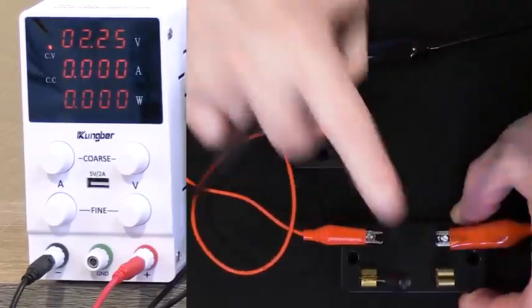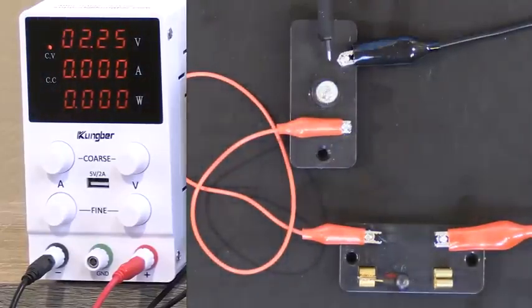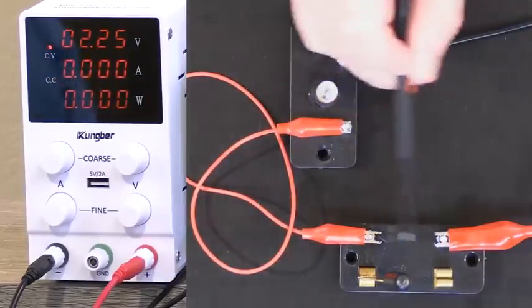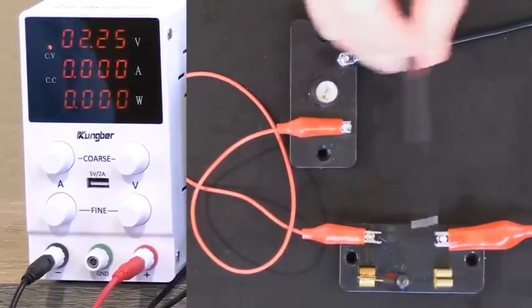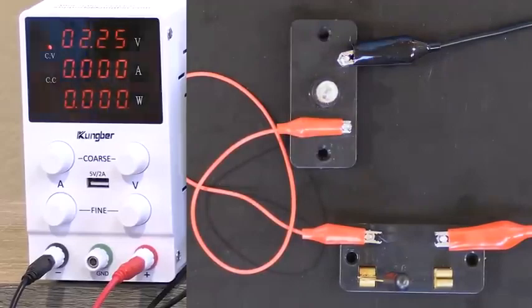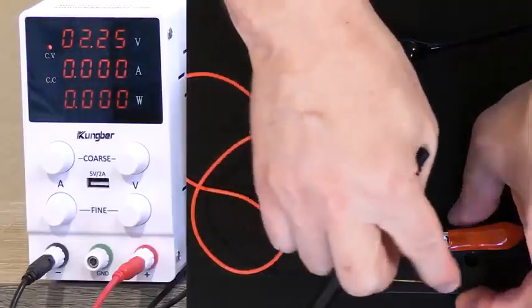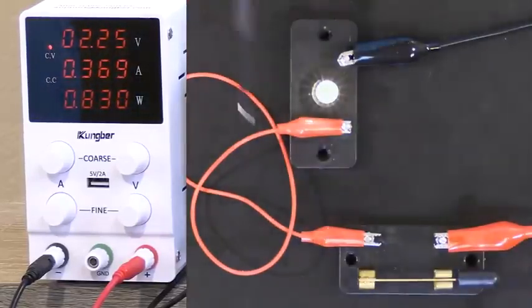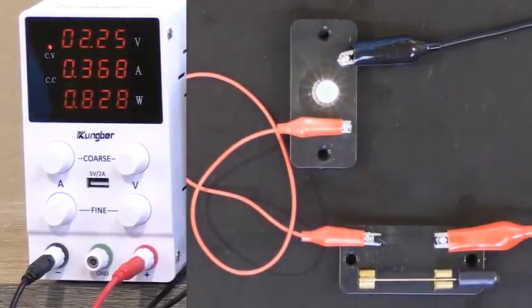Now, if I interrupt the flow of electrons, if I just open this thing and I break the circuit, and now there is no way for the electrons, if they were to get here, there's no way for them to go back through this switch because it's now open. And that's called an open circuit. So we're going to talk about open circuits, and in just a minute I'll show you what a short circuit is. An open circuit is just a circuit that has been essentially opened up and disconnected. It prevents the circuit from being closed so you can't have any current flow. Once we close the circuit again, then of course the light bulb is immediately illuminated again.